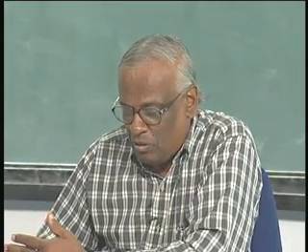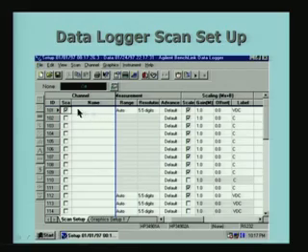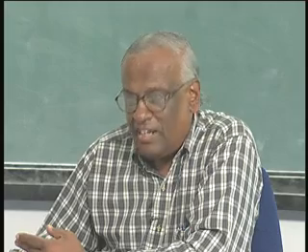It may be measuring simply a current or a voltage, or it may be measuring a temperature. So, I can say temperature 1, channel number 1 corresponding to temperature from thermocouple 1, for example. I can write it here. The range is auto, that means the instrument will determine the maximum and the minimum, automatically it will change the range, so that you do not have to intervene.